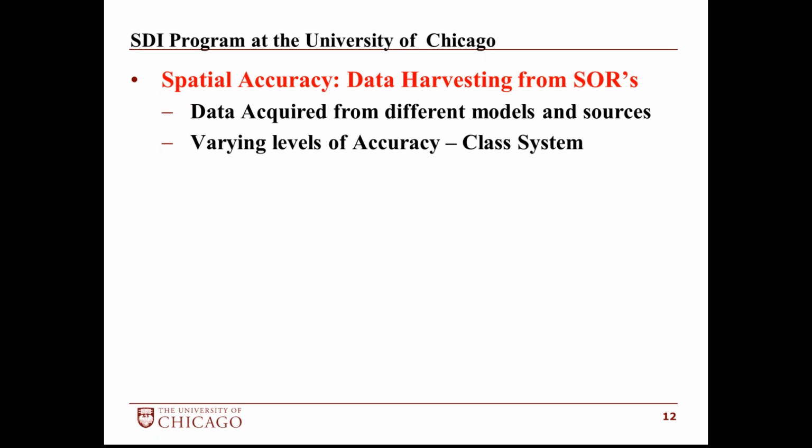So all this has to get meshed together in one coherent system, and you have to keep track of that in the substitution process when you're trying to bring all this data in, where you don't want to take out class 1 data and replace it with class 3 data, even though it may actually be, quote, newer data. Its level of accuracy may not necessarily be up to speed with what's already in the system. Oftentimes the data is not coming in state plane. That's particularly the case in BIM. We're going to fix that with the BIM standard, where we adopt that and put that in state plane or make that a requirement, and try to deal with our vendors on this to make sure that the data comes in right out of the box, ready to go in state plane coordinates.